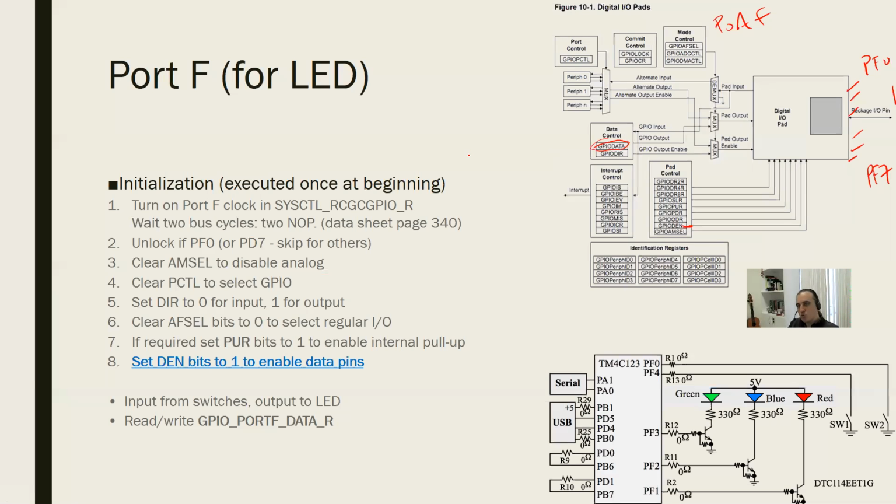GPIO data is also a register. It's a 32-bit register, but the first 24 bits are reserved. And the last 8 bits, if you write any of them, and if you configured your device to be an output port by selecting the direction register, we have configured it as an output port. When you write something to it, these pins will change.